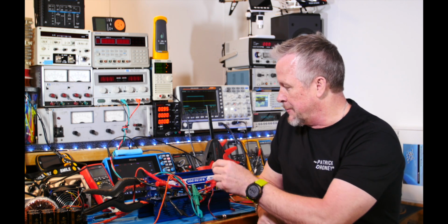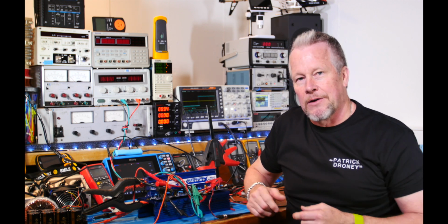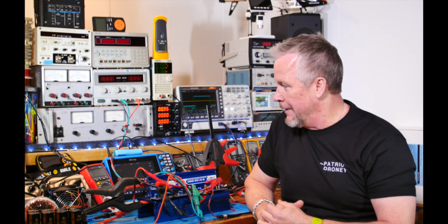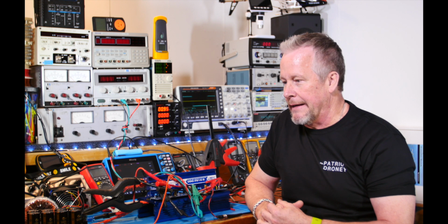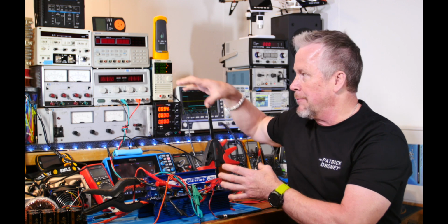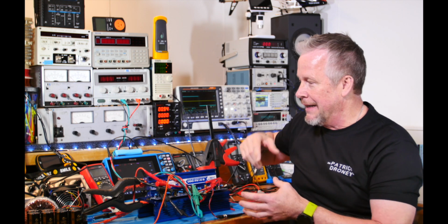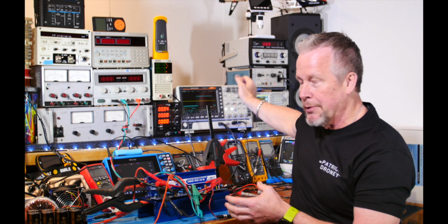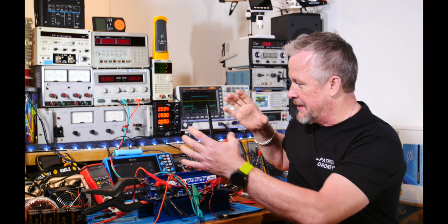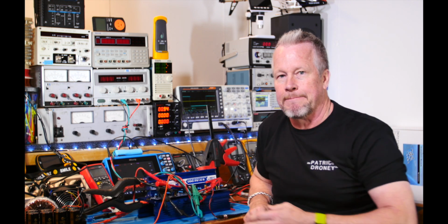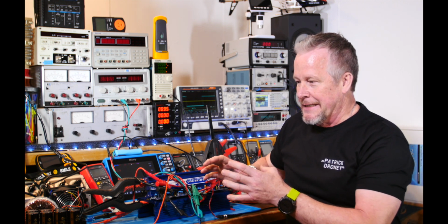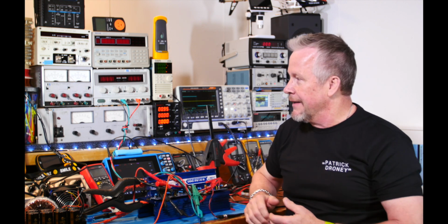When I was trying to set the optimization by adjusting this bias current, for this range of voltage that you can get to set the amount of current, I didn't really see a benefit from that. I think it was because as it was getting better, it was actually causing a bigger problem with this interplay, which has to do with the amount of signal we're putting out and the power supply. So my idea was to separate this from the AC to DC power supply, test them separately to begin with, and make sure that I wasn't seeing problems caused by the two interacting.